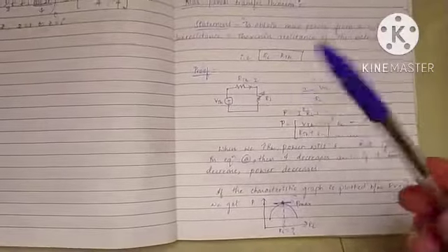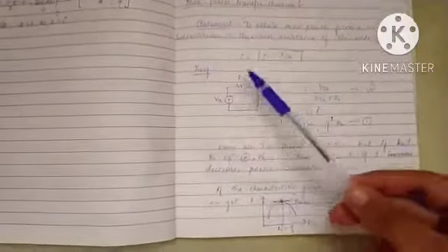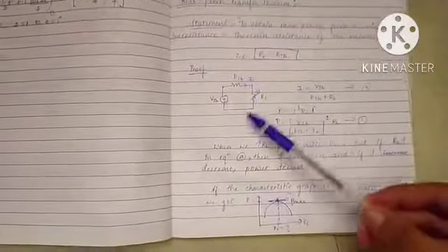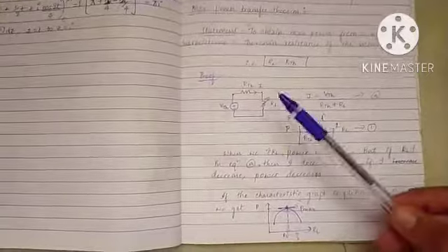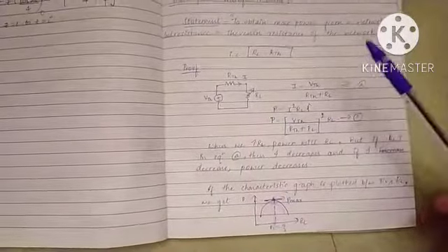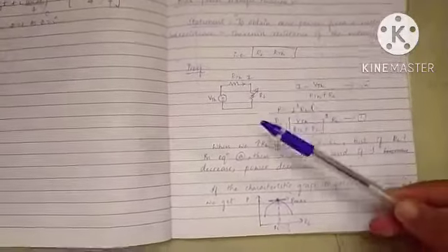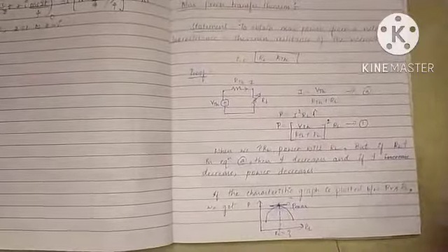When you have learned about the Thevenin's theorem, you have seen the circuit diagram where VTh and RTh will be connected in series to your load resistance. Here, when we try to calculate the current, it will be equal to V by R. Here it is VTh by RTh plus RL, as load resistance is connected in series with VTh and RTh.